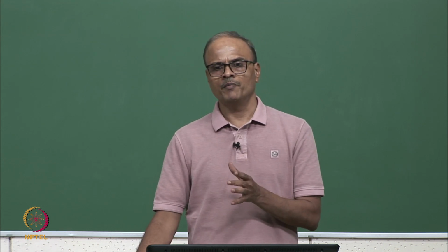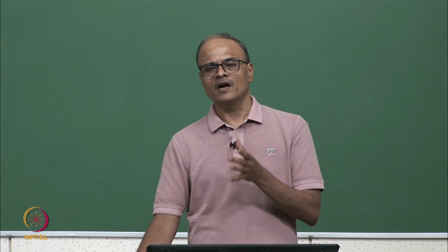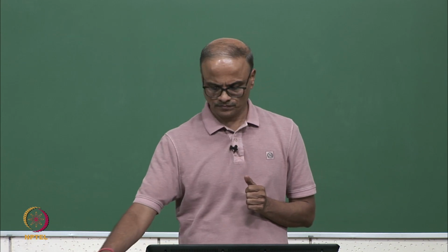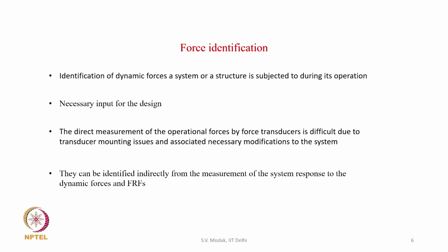So, it does not depend on direct measurement, but it performs indirect identification from the measured responses and measured frequency response functions. So, these forces can be identified indirectly from the measurement of the system response to the dynamic forces and FRFs. Instead of measuring the dynamic forces, what we measure is the response. Measurement of response is much easier as compared to direct measurement of the forces. So, we measure the response of the structure to the dynamic forces at several points. We also measure the FRFs, and if we have a model, then we can also identify FRFs from the model and then use those FRFs and the measured responses to identify the dynamic forces.